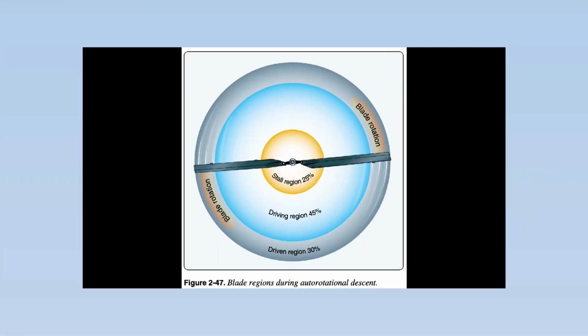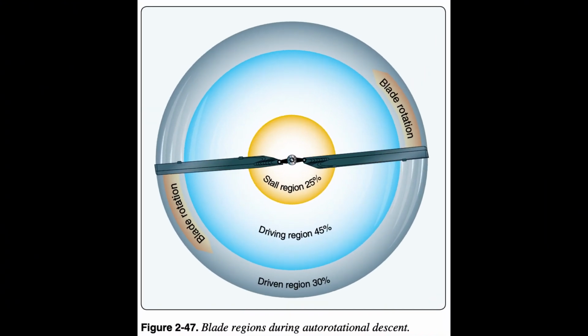Vertical autorotation. Most autorotations are performed with forward speed. For simplicity, the following aerodynamic explanation is based on a vertical autorotative descent, no forward speed, in still air. Under these conditions, the forces that cause the blades to turn are similar for all blades regardless of their position in the plane of rotation. Therefore, dissymmetry of lift resulting from helicopter airspeed is not a factor.